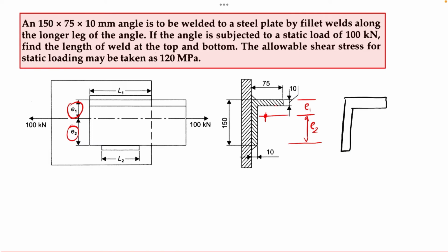So this is in this L shape, and the dimensions of the same thing are given, 75. Here I will be finding our origin, and the axes will be along this one for finding the CG. So these dimensions I will be marking. This is 10 mm, so I will be taking this up to this part. This is the first part and this is our second part.